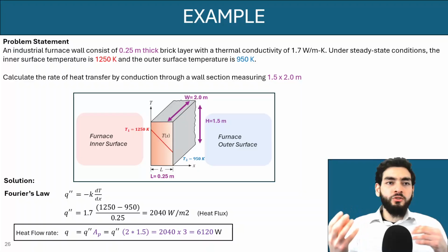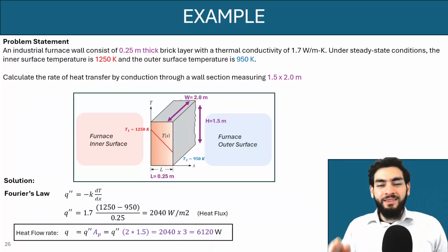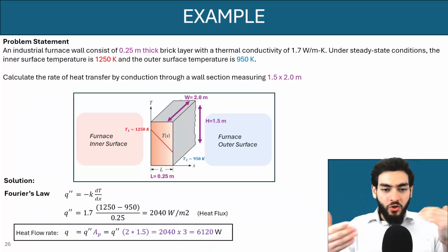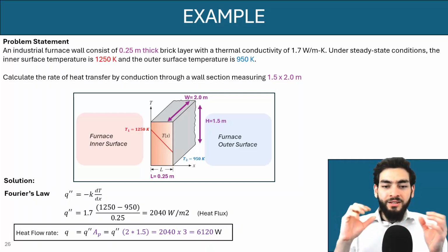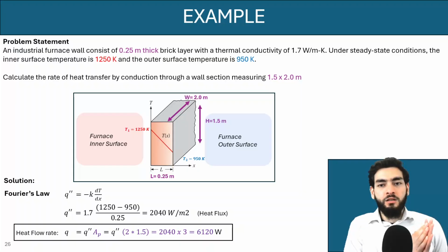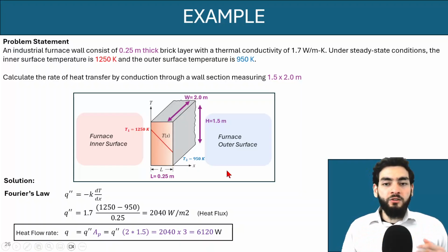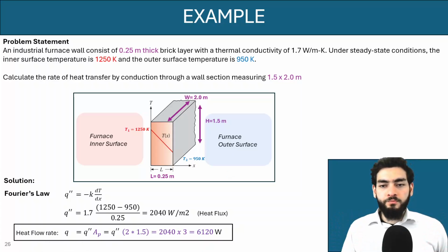You can also do a sensitivity analysis yourself. You could use the thermal conductivity at temperature T1 and at temperature T2 and solve the problem twice, and you're going to realize that the difference in both answers is very minimal. I'm saying that because if you actually do this exercise, it helps build your intuition as an engineer. And this is also very important: I don't want you to memorize things. I want you to build the right intuition.